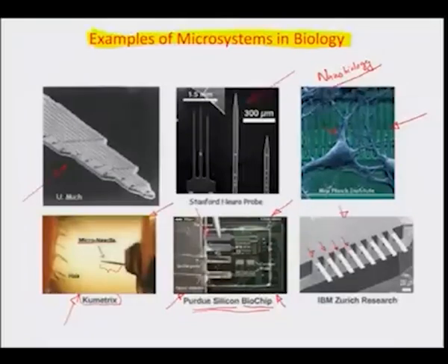In fact, this work done for the first time at IBM Zurich Research indicated that deflection of these cantilevers can be synergistic with some of the binding events that may happen on top of these cantilevers between capture probes, which are very intelligently placed on top of each cantilever, and a target molecule which may come and bind.